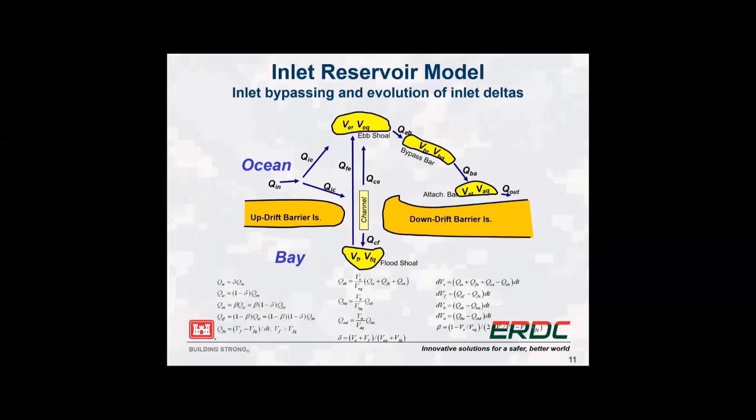If unit one is the ebb shoal, the bypass bar could be one quarter of that, and you can start that kind of estimation. But my experience is that for bypassing sediment from updrift to downdrift, if it's stable, you can have a very clear trend with a dominant downdrift direction.